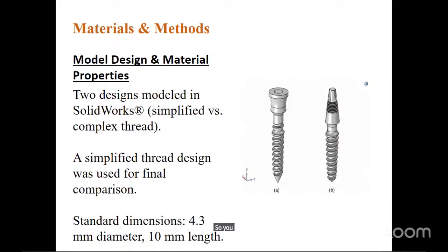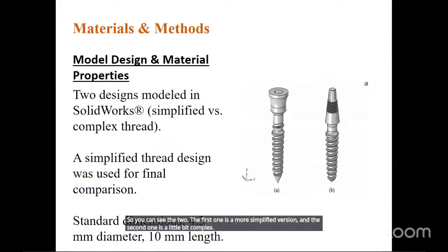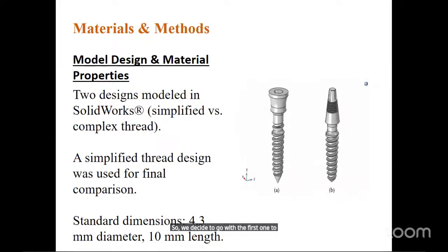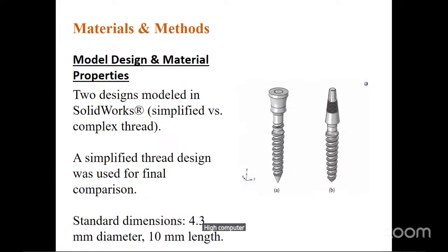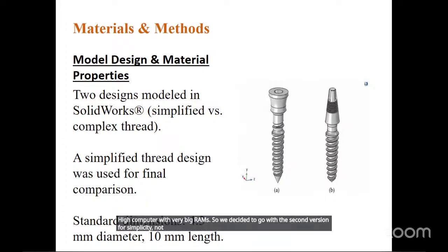You can see the first one is a more simplified version and the second one is a little bit complex. We decided to go with the first one because, using the second one, we can see thread above and thread below, and each thread consists of hundreds of faces. To simulate threads with more faces, sometimes the simulation might not even work, or it will require a very high-end computer with very big RAM. So we decided to go with the first version for simplicity, not for any superiority of design or anything. For simplicity of simulation, we chose the first design for this work.